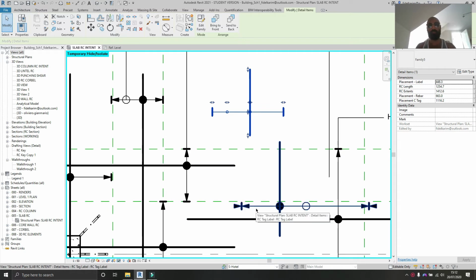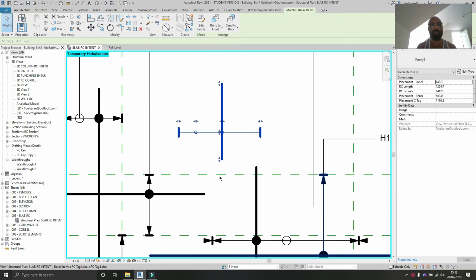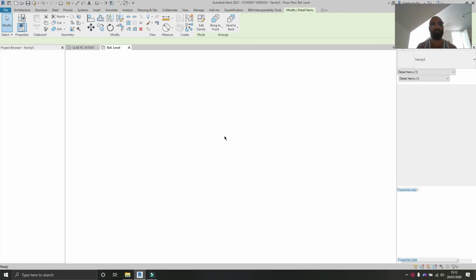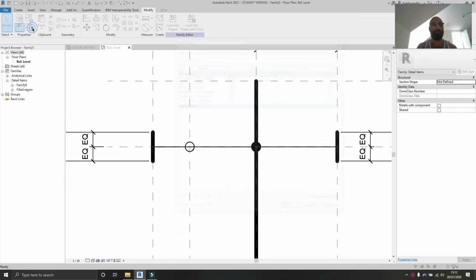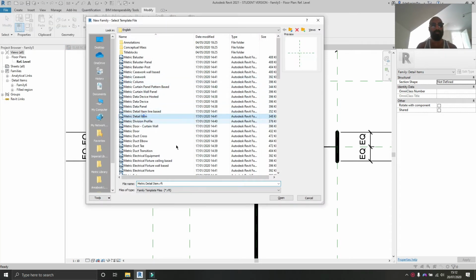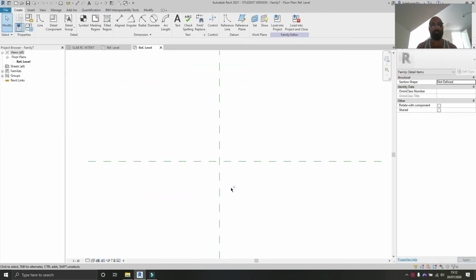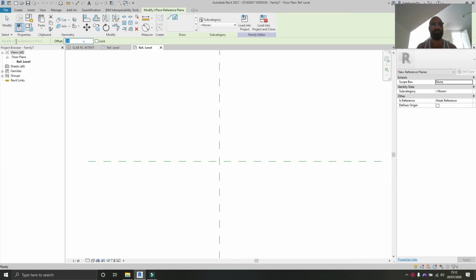All we need to do now is toggle the visibility and work with the scales and add the arrows. So first I'm going to create new arrows, just like we did with the circles. And so to do that, I'll say file, new, family, detail item, there you go. So create this, select this, we'll type RP actually, there you go, say 100, offset, there, there,